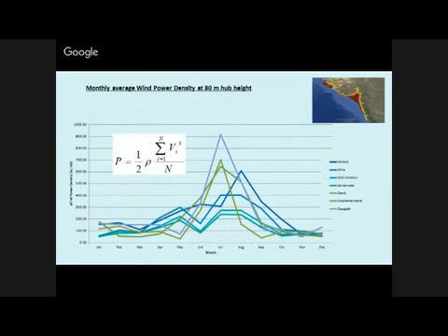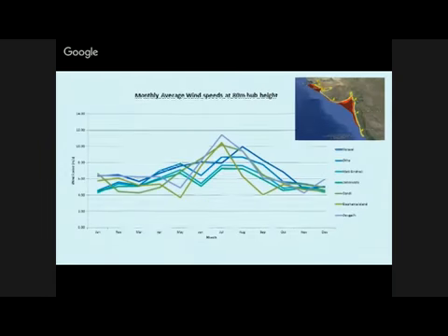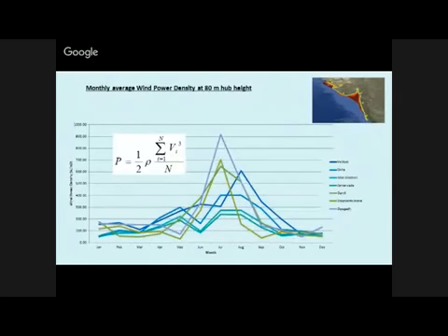Once the wind velocity is there, this velocity is converted into wind power, and we know that power is proportional to the cube of wind velocity. A slight increase in velocity, almost a 29% increase, will create double the power. That is the main salient feature, because power is proportional to the cube of wind velocity. Again, particularly in coastal areas, between the months of May and September, peaks are there in almost all the major data, and this peak is very suitable for electricity generation using wind energy during that particular season.